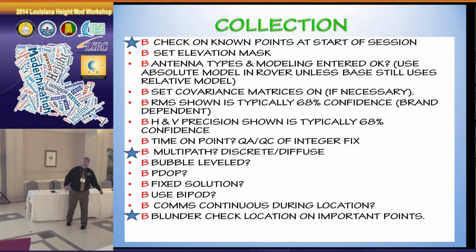If you need to, whether it's a Trimble QC1, QC2, or Leica, or whatever it may be, make sure that you're setting that data that gives you the covariance matrices on, and all that is producing an error ellipse, if you will. So back in the software, if you did more than one location, you can actually tweak your location if you have that set on. Download your data, your post-campaign real-time work can be tweaked if you have a redundant location. Just saying.